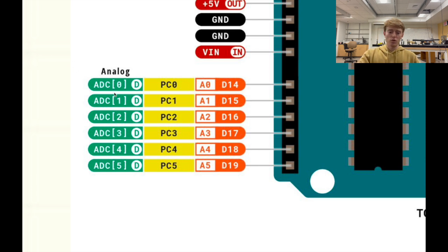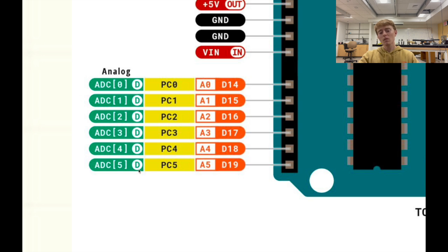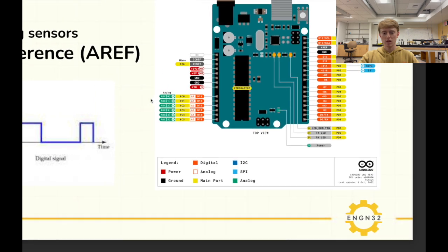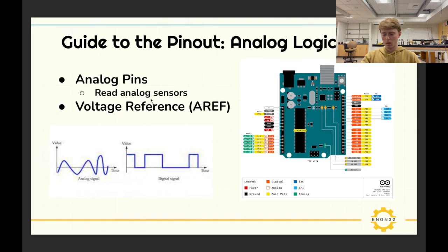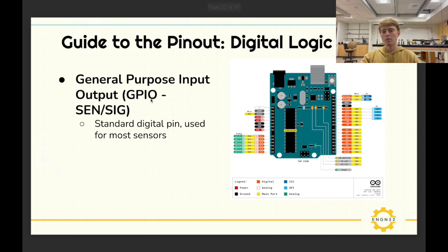They have a pressure transducer, and the signal from that pressure transducer needs to be digitized. And so to look at that pressure transducer signal, we bring it in through these analog to digital converter pins, okay? So that's another example. But all these pins are analog to digital converter pins, and so they have a special purpose, and that's just something to keep in mind, and that's what they're used for, okay? And by the way, we'll talk more about analog to digital conversion and what the difference is between analog and digital signals next time in our beginning to circuits studio, okay?